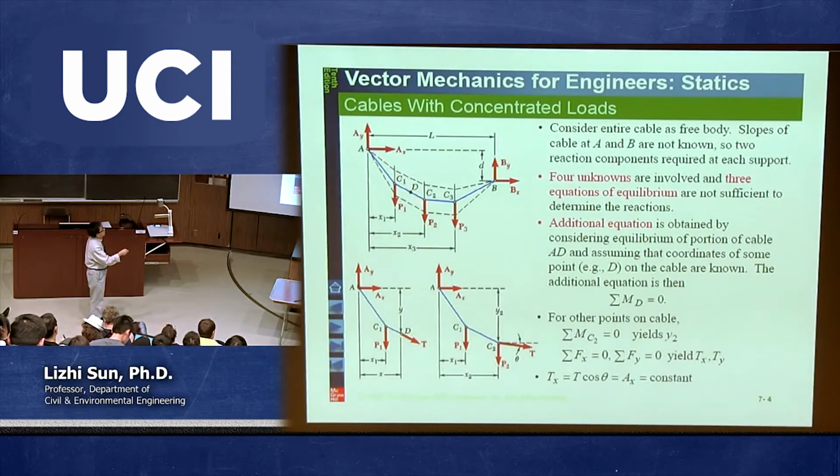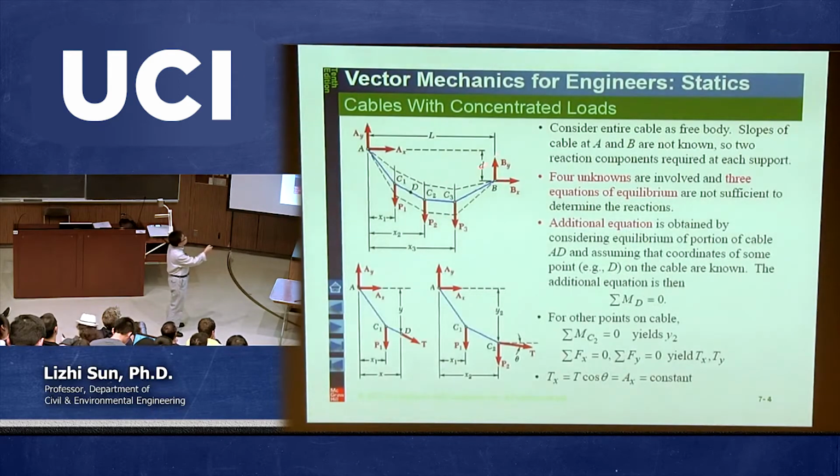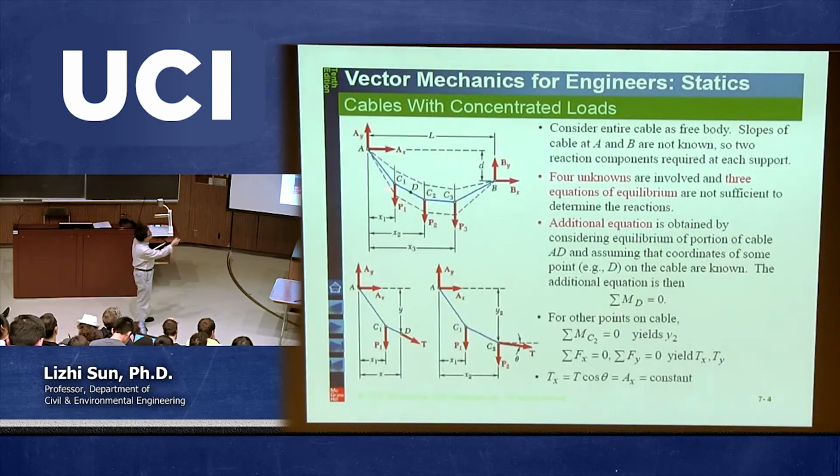So this is the cable AB again. We cut point A, and we gave two reactions, right? These reactions are called AX, AY, which are unknowns. And then we cut point B, which is another pin, and we gave another two reactions. Assuming we know these forces, let's just put those forces here. Now, this is what we call the free body diagram for the entire structure.